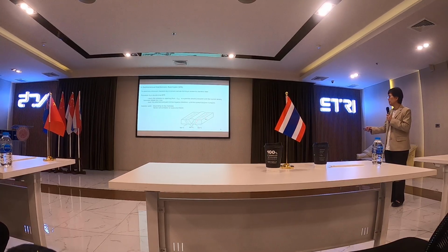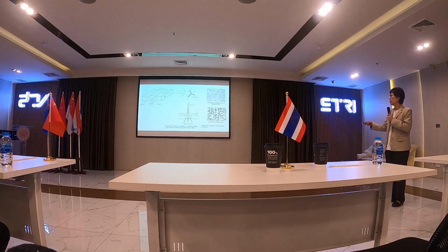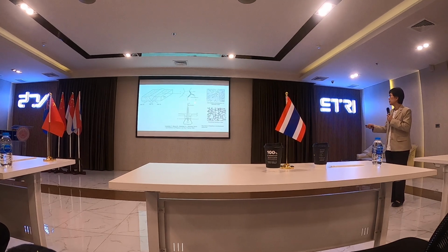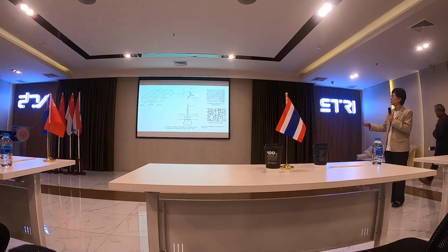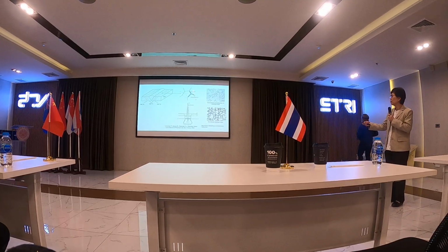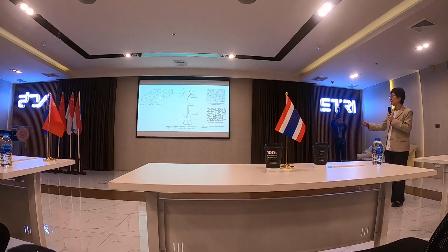In this region, the stainless steel with chromium, in this case 18%, the chromium will diffuse to the grain boundary and form chromium carbide at the grain boundary and cause a chromium depleted area around it. So that means along the grain boundary, they have a chromium depleted area.